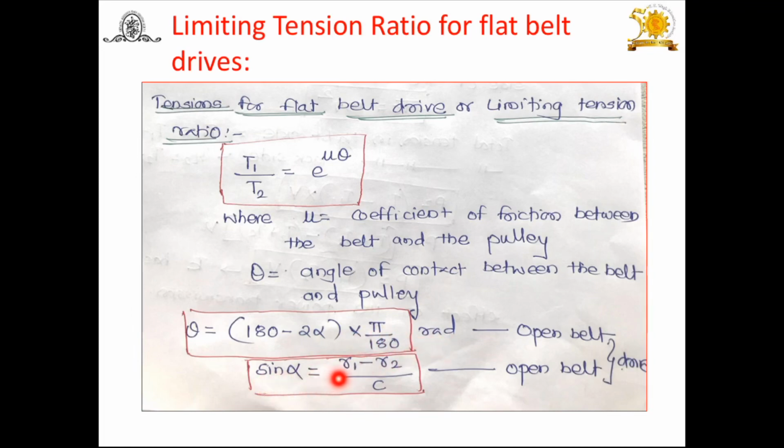Again sin alpha is equal to (R1 minus R2) by C, or in terms of capital D minus small d, by 2C. In this fashion we can find it.